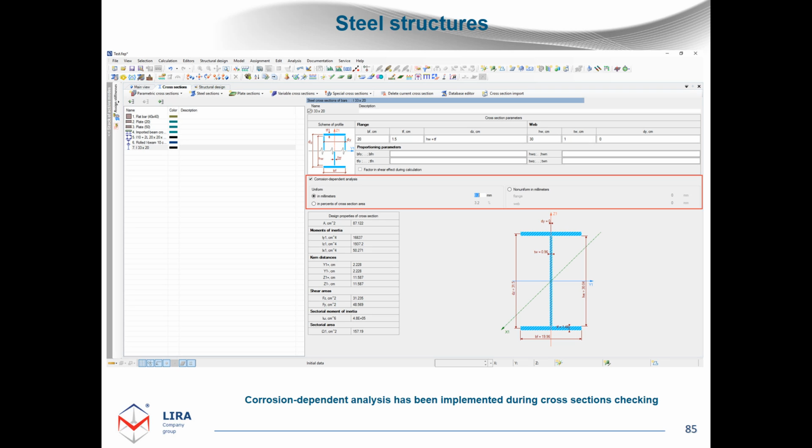The program will automatically correct the cross-section form and recalculate all stiffness properties. After that, new stiffness properties will be accounted in stress analysis. Also, the new form of cross-section will be analyzed. Therefore, all points where stress is checked will be determined in places where there is steel, in fact.